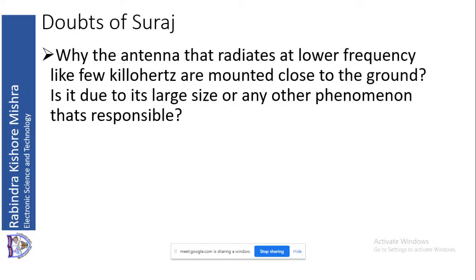If the antenna is near the ground, then there will be ground wave communication. Like we discussed ionospheric communication, there is something called ground wave communication. Earth crust has a conductivity, so the earth will conduct it. But since it has a conductivity, it will be attenuated at a short distance. Earth will conduct it over about 20 to 25 kilometers maximum, depending on the conductivity. So line of sight and earth conduction, these two are there.